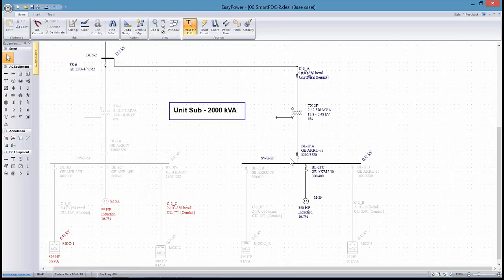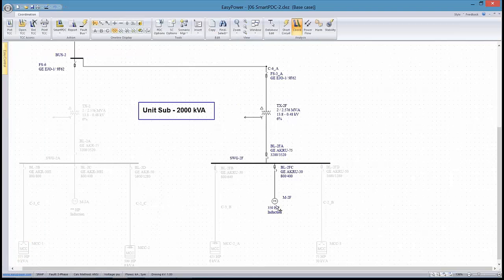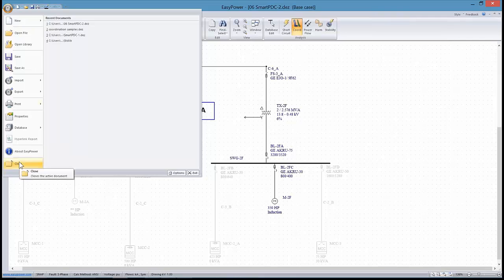The reason for isolating it and making it simplified is that now I can actually go into short circuit focus or coordination, independent of whatever problems I have out here. I can go through the analysis and see why the data is important, and as I go back and look at what's missing in these other elements, I will understand either my data collection was inadequate or my data entry was inadequate. So that's just a word to the wise.